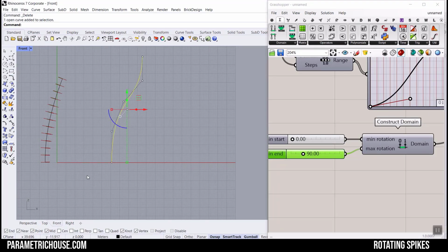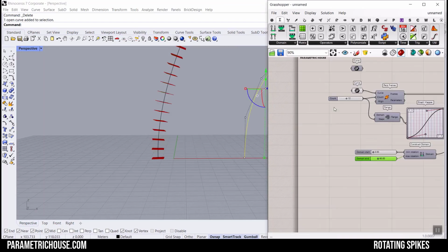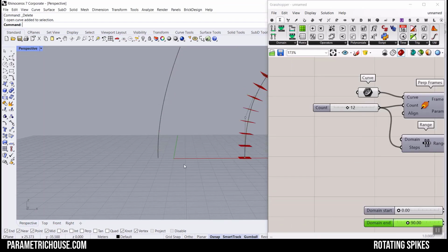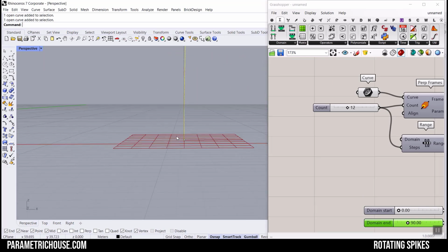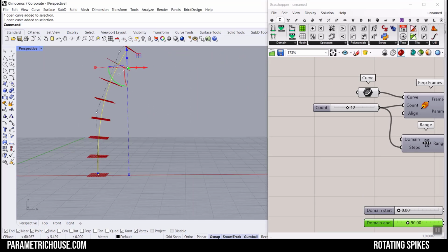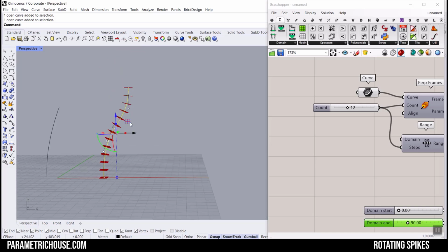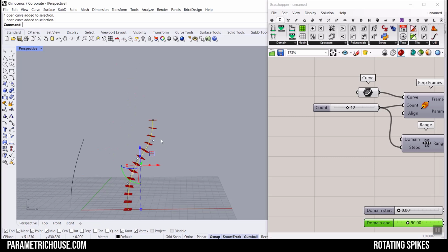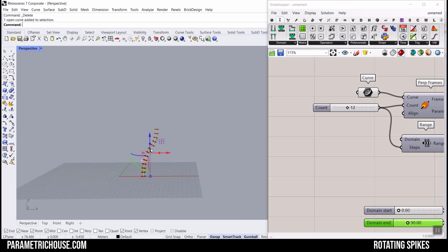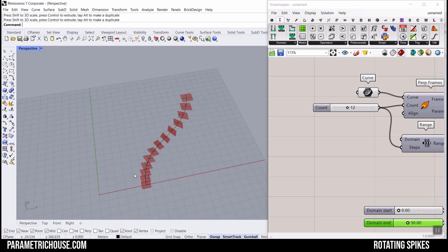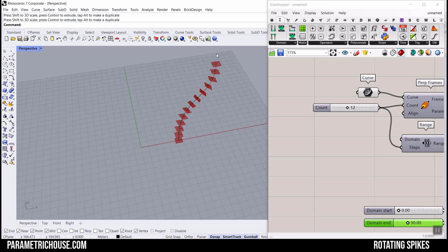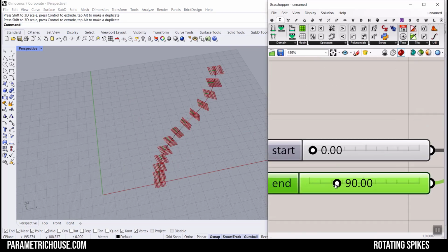And now you can see if I give this as the base curve, it's going to be perpendicular at the XY plane. The reason here is that the control points have some sort of magnitude, so it's going to assure that it's in the XY plane. It's going to be the same for the end of the curve. Maybe we can scale this if we want to change the form. Okay, and you can see obviously this is the X, and now it's going to go like that. We can control the minimum and the maximum.